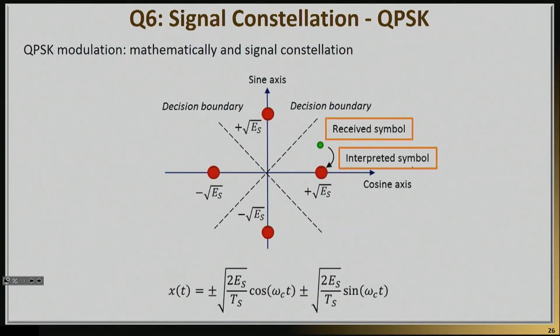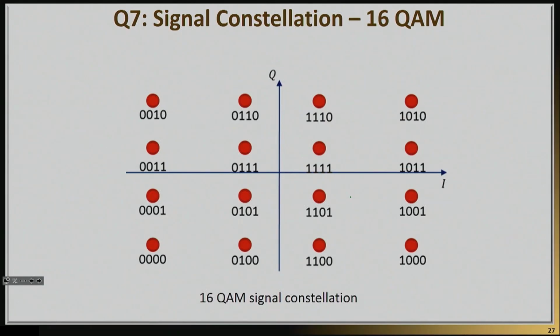All right, let me give you an example of the QPSK signal constellation diagram. And as I mentioned before, we are going to receive something in real life that will not really be on top of any of the ideal symbols, and then we're going to have to make a decision. So usually, the minute you see a signal constellation diagram, you can decide on decision boundaries, which, given that everything is equal probability, you're likely going to put at the center, in the middle, as I have done here. And we show you a few other images.